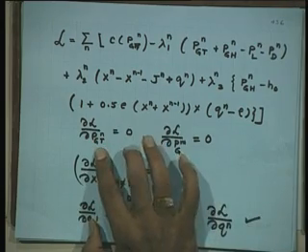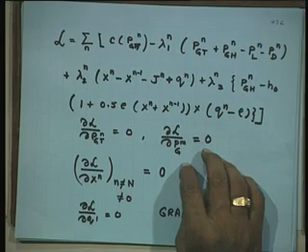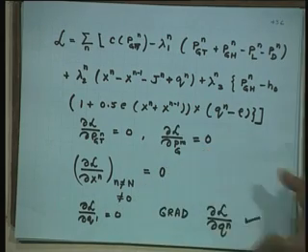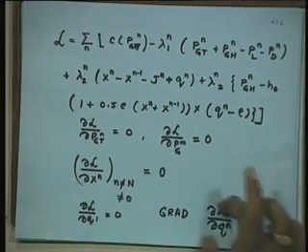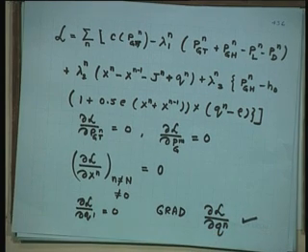Differentiate with respect to all the dual variables, Pg, all dependent variables rather, and then calculate gradient. Gradient means control variables. What are the control variables here? Only water discharge. And then see if it is 0. If it is 0, you converge, you optimized. Print out data, what is hydro generation, thermal generation, loss, storage, discharge for your benefit.